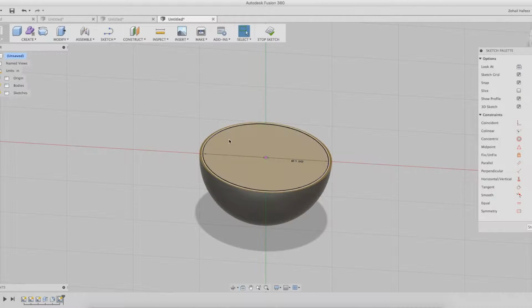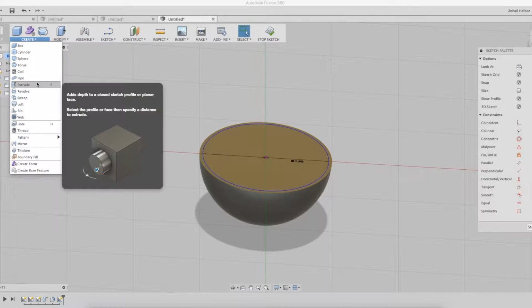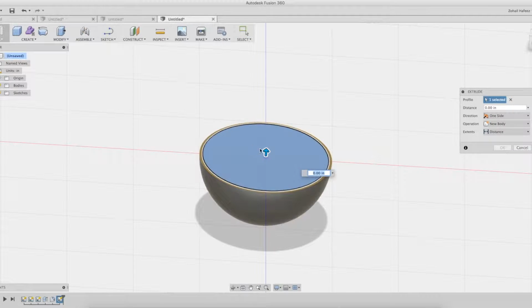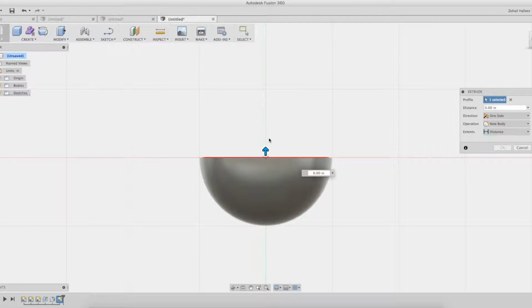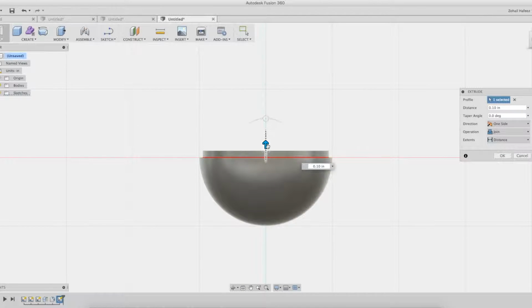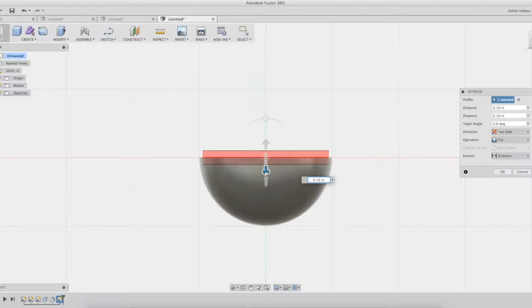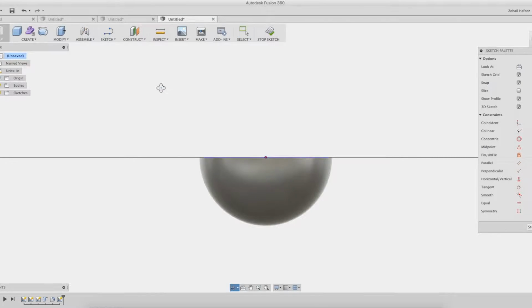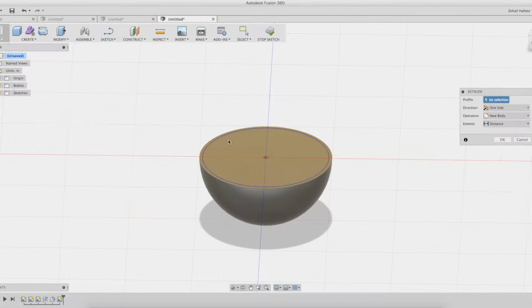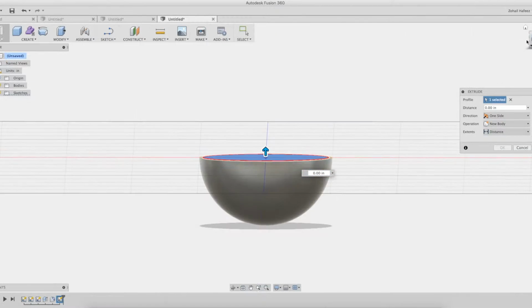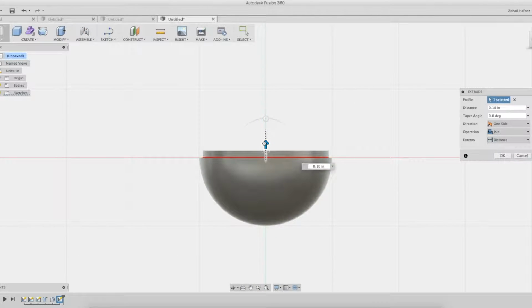So you can see we kind of sketched it there. What we want to do is extrude it, make the object 3D now, that gap that we want. You can change the view to get a better idea. So we can just pull it up 0.1 inches or 0.2. 0.1 looks better, so we'll stick with that. Now, if you just choose sides, it would kind of cut through the surface, so you just want to use one side. And we'll make that 0.15 inches.